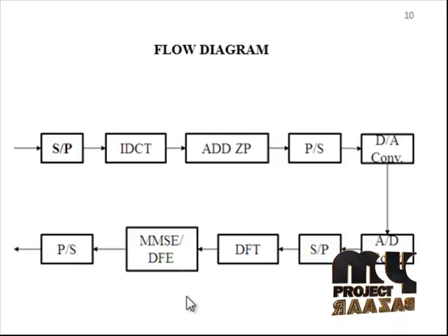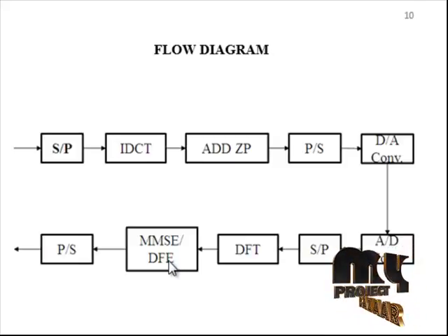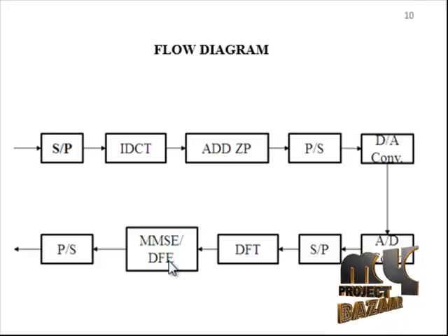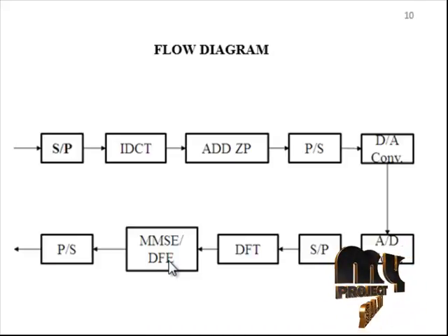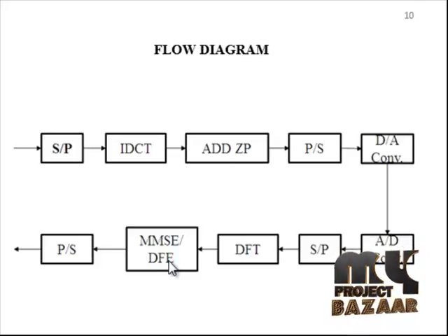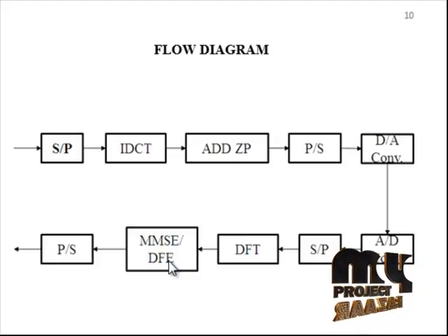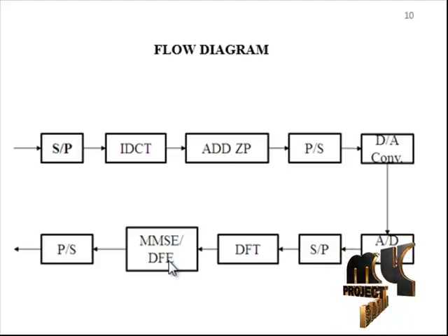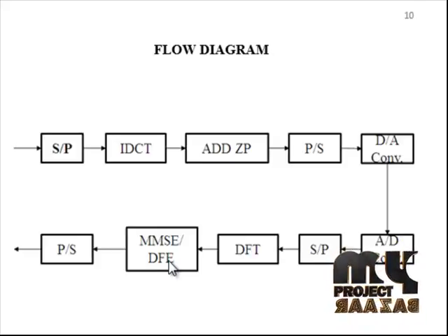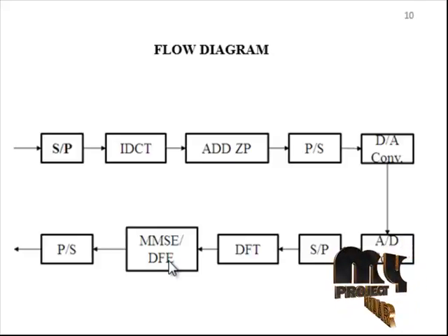Next, the DFE or MLSE equalizer has been used. Channel equalizers are either linear or nonlinear. Nonlinear equalization is needed when the channel distortion is too severe for the linear equalizer to mitigate the channel impairments. An example of a linear equalizer is the zero forcing equalizer, and as the name implies, it forces ISI to become zero for every symbol decision.